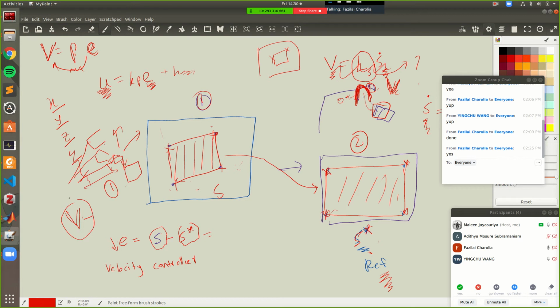Can I ask, the coordinates of the feature is a 2D position? Exactly, right? These features could be anything. It could be 2D coordinate values, it could be an entire patch on an image. And how the error relates to each of these components in the velocities depends on the L matrix. Can it be 3D? Yeah, it depends on this L matrix.